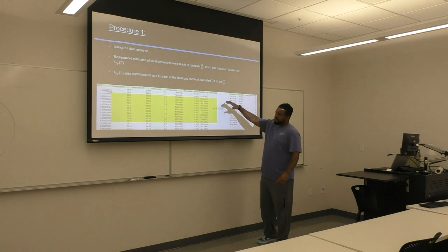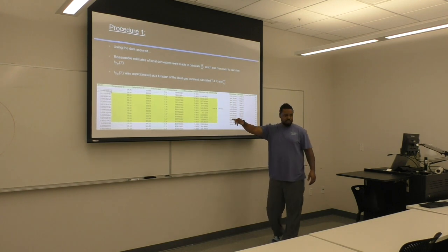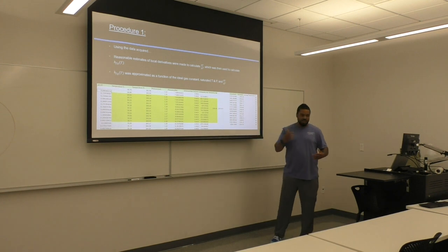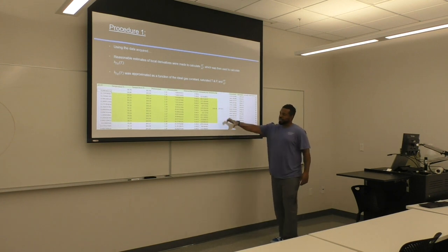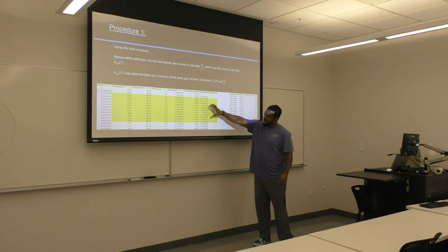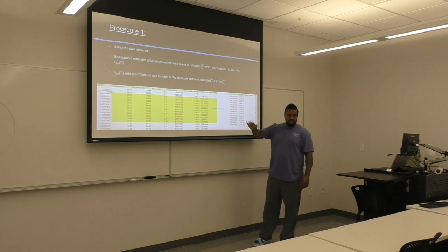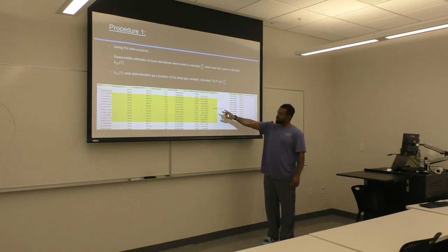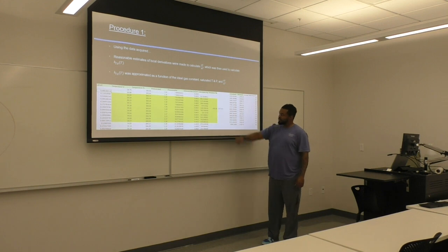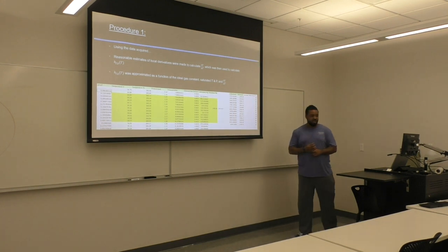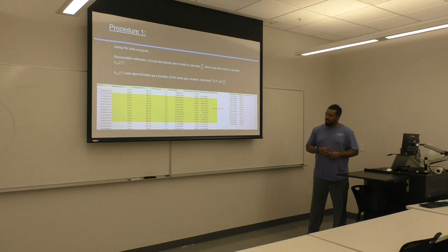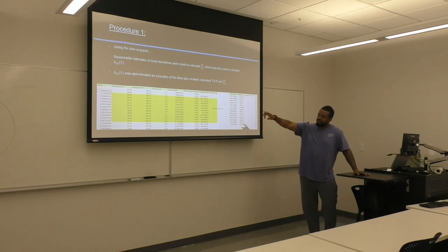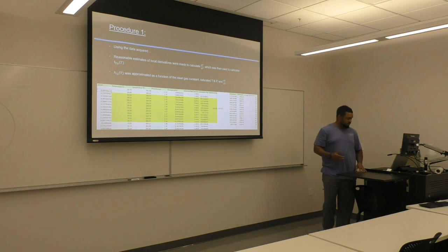But I wanted to show here that in the steam tables, they do temperature in increments of 5 degrees. So it's 30, 35, 40, and so on. So what I ended up doing with our data was averaging close to that 30 degrees and so on, to compare my tabulated latent heat versus my calculated latent heat. I also want to mention that temperature started from 29.75 degrees Celsius and ran up to about 99 degrees Celsius.